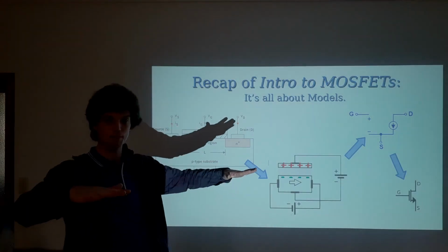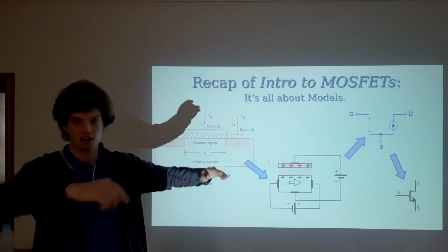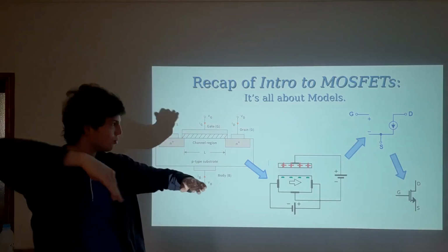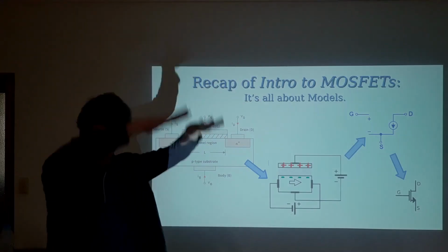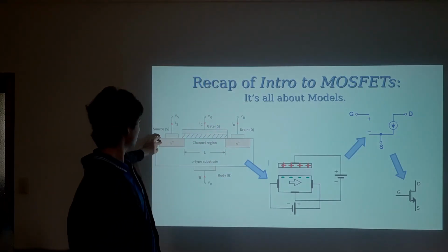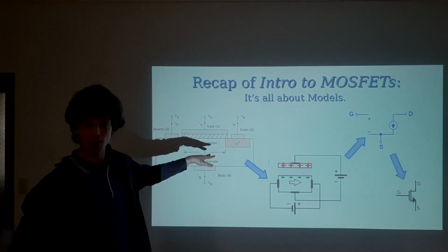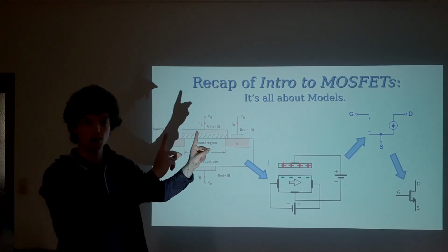Like, they'll lay down a base layer of silicon, then deposit on, say, N-type silicon, then use a really precise laser to erode away the bits they don't want, leaving just a couple of chunks of this N-type silicon. Then they'll deposit a flat layer of P-type over the whole lot, erode away the bits they don't want, and they'll be left with this NPN structure that looks pretty much like that. It's absolutely fascinating. But that's not the point of today.